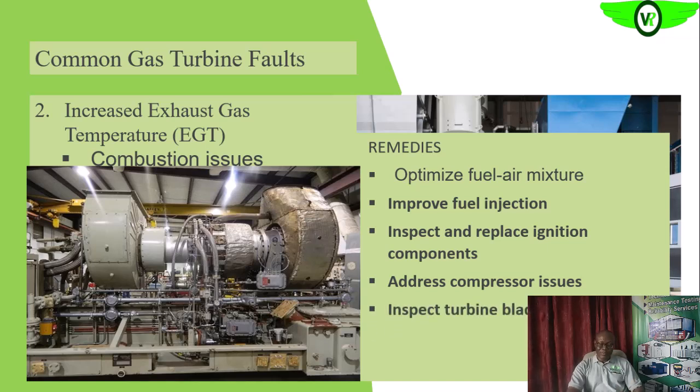Then the turbine blade, at regular intervals and at any available opportunity too, we want to inspect this blade to see that nothing is wrong with them. So we want to carry out BORESCOPE inspection on this blade, even the compressor blade too. Look at if there are deposits on them. Look at if there are signs of distress in them. Look at if there are cracks, breakage, or missing blades in the rotor. So all of these we want to be sure of.